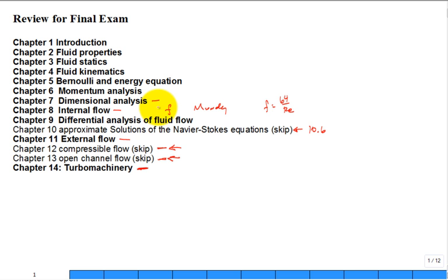Dimensional analysis. Because fluid mechanics doesn't have a lot of analytic solutions, you rely on experimental measurements and you extrapolate those. So we talked about C sub D, the drag coefficient, as a function of Reynolds number. How do you come up with the structure of why we're looking for only the drag coefficient as a function of Reynolds number? Well, you can justify it using dimensional analysis. It leads to the grouping of parameters and the relationships.